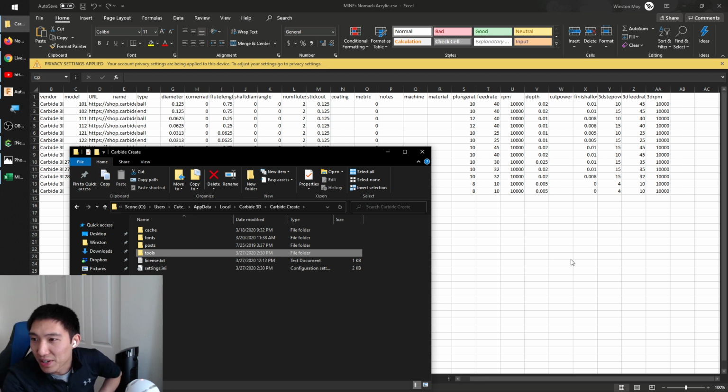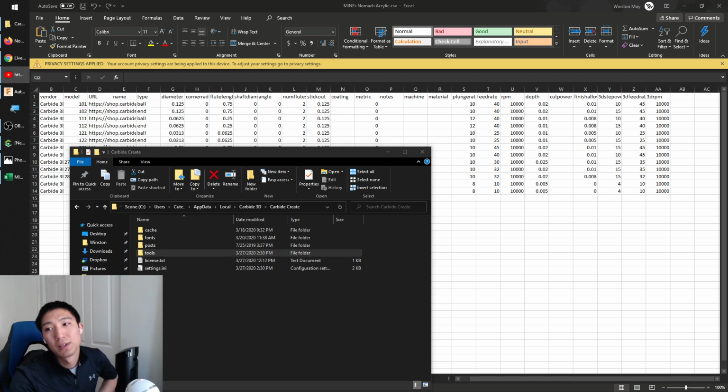I find on the HTZ I can use the same chip load as you mentioned in your video for single flutes, but I can cut significantly deeper, up to 7mm with a 1/4" cutter. So yeah, you can definitely push faster than the speeds and feeds I recommend, but a lot of it just comes down to how adventurous you are feeling. I have used a 1/4" cutter on a HTZ Shapeoko running a router, not a VFD spindle, up to about 0.3 inches deep. So that's about 7-ish millimeters.